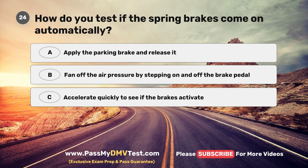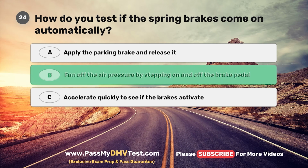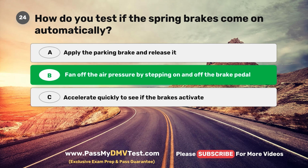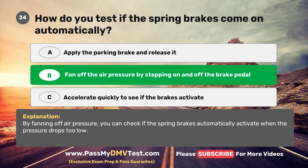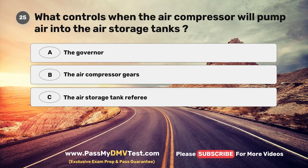Question 24. How do you test if the spring brakes come on automatically? A. Apply the parking brake and release it. B. Fan off the air pressure by stepping on and off the brake pedal. C. Accelerate quickly to see if the brakes activate. The correct answer is B. Fan off the air pressure by stepping on and off the brake pedal. By fanning off air pressure, you can check if the spring brakes automatically activate when the pressure drops too low. Question 25.